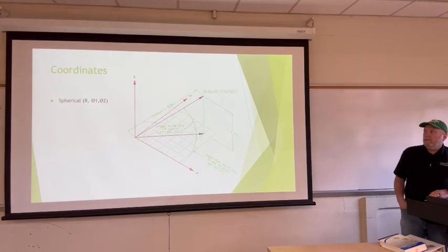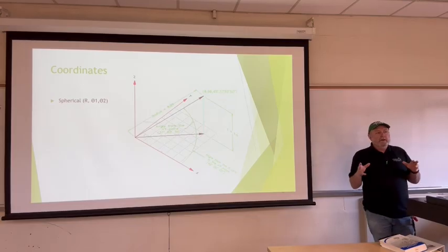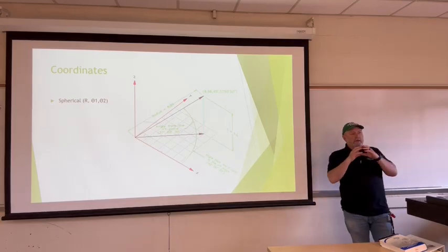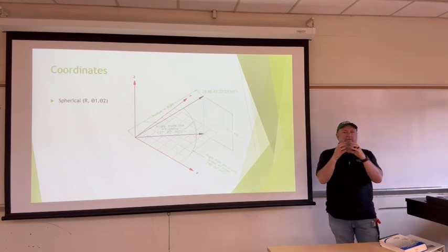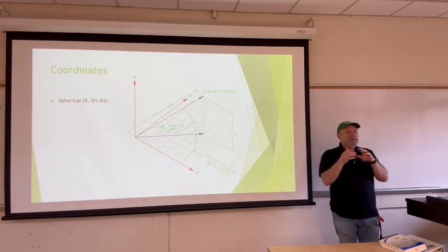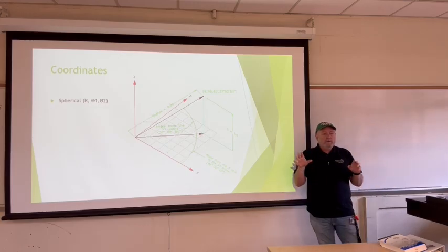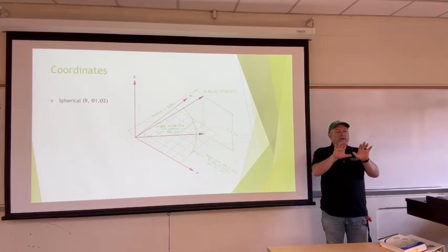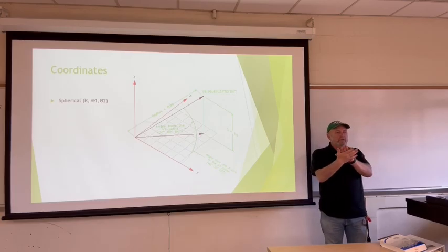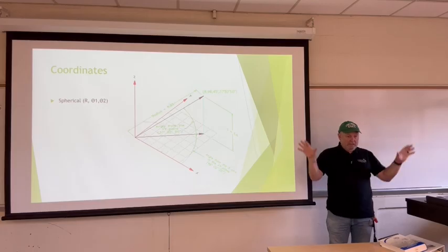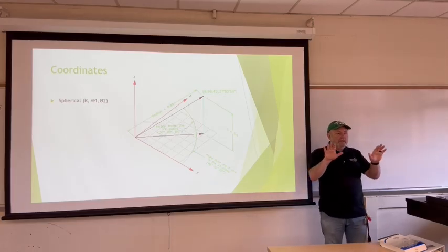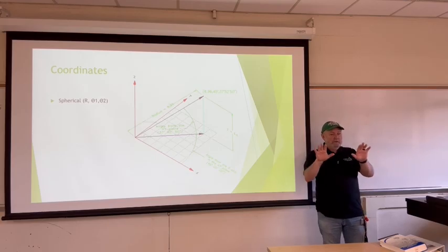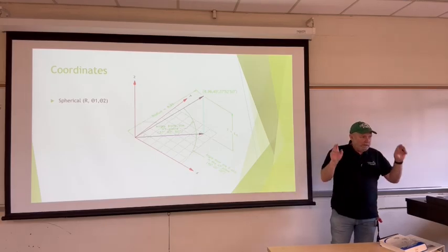Well, the fact of the matter, from a geodetic standpoint here, we have an ellipsoid defined. Again, a mathematical, smooth, perfect shape, a rough shape of the Earth. This is what we use to establish our latitudes, longitudes, and elevations. For what we use here in North America, that ellipsoid is essentially best fixed to the North American continent tectonic plate, if you will. So our coordinates essentially are moving with that tectonic plate, and they don't move. They do, but they don't.